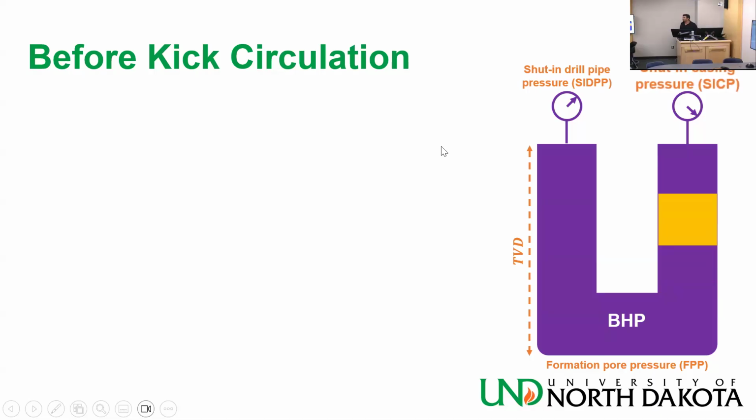There you go. So you see it's moving up, right? As it's moving up, it becomes taller and taller. You don't see it getting taller, but I set it up to become a little bit taller as it's moving up, right? And as you move up, the shut-in casing pressure becomes bigger and bigger, right? Because it's what you guys told me earlier.